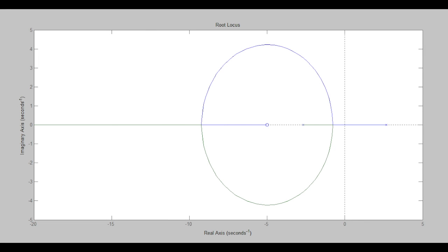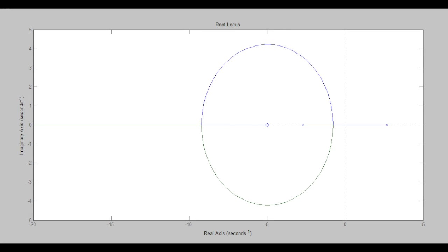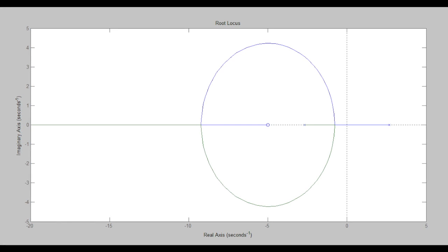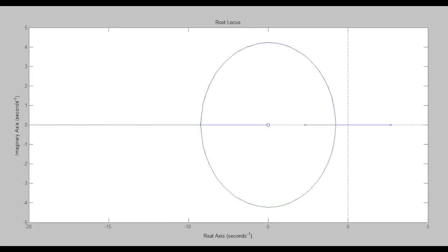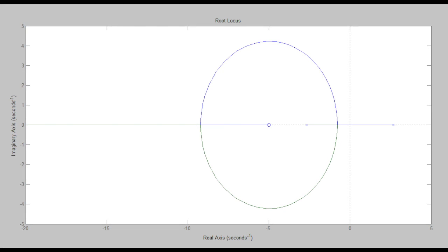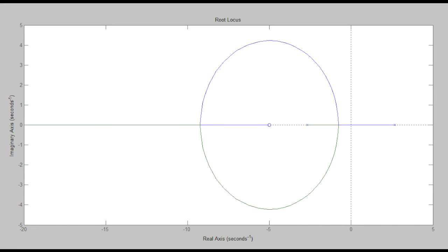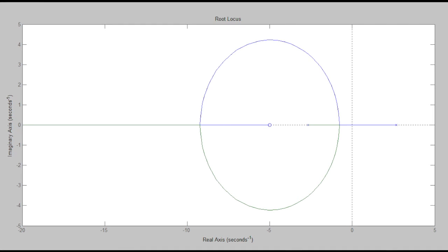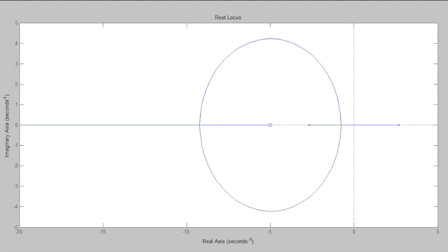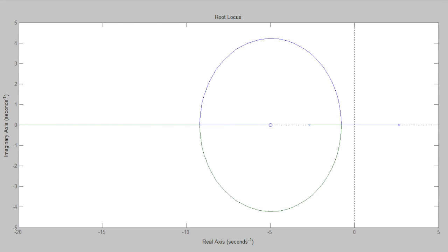In turn, this leads us to the root locus plot shown here. As you can see, there are two open-loop poles, which stem from the transfer function itself, and then an additional zero, which comes from the controller that we plan on using. Here, this is a PD controller, which puts the zero farther to the left of the leftmost pole, which in turn provides a track for the root locus plot shown, so that both poles will be pulled onto the left half plane and create stability upon the increase of gain to the appropriate level.